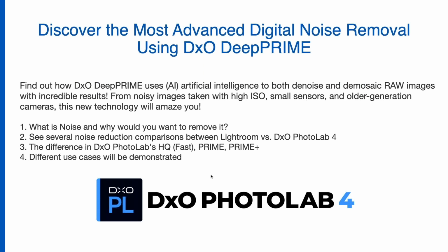Now, the reason that sensors are getting better and better over time, every year that goes on, we have higher ISO capable cameras. You used to be able to shoot maybe 800 ISO, and at that point was the limit. You shot higher than that, the camera looked like rubbish. Today you get cameras where you can shoot at 25,000 ISO and it still looks unbelievably good, especially if you're used to shooting at the lower ISO rates, because those sensors are just getting better and better tuned to be able to amplify the signal without creating artifacts, or creating fewer artifacts. There's never none, it's just creating fewer of them. So anyway, that's where this comes from.